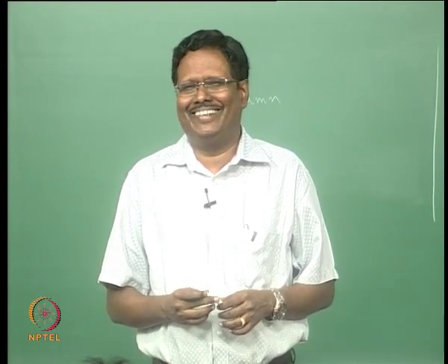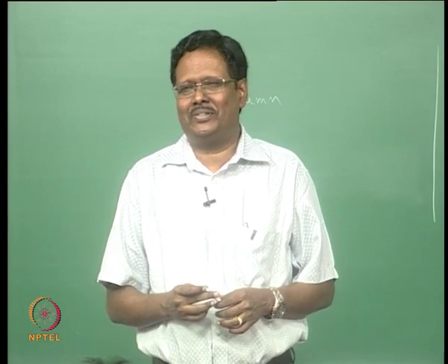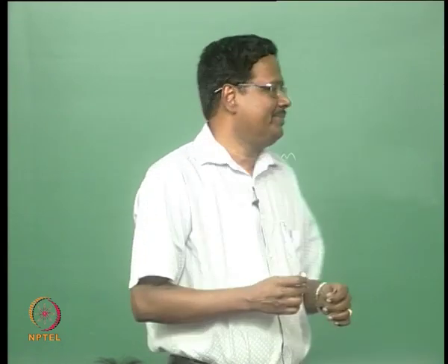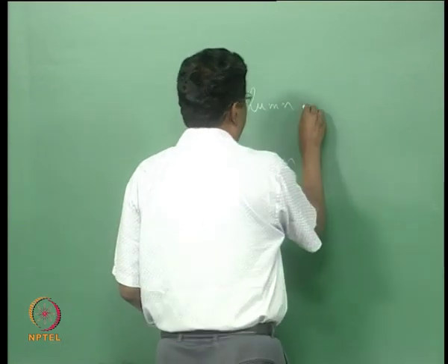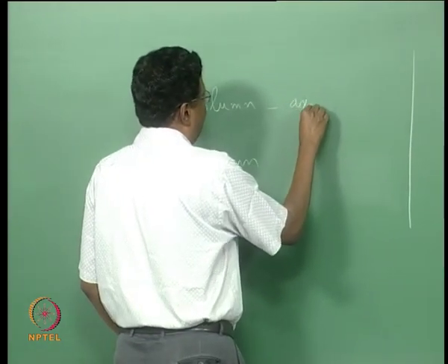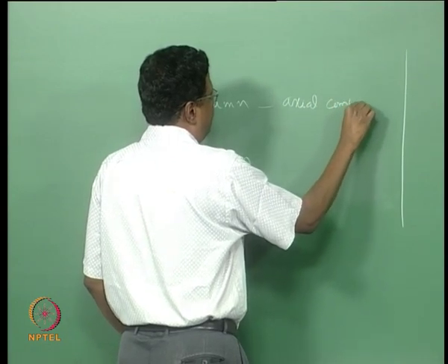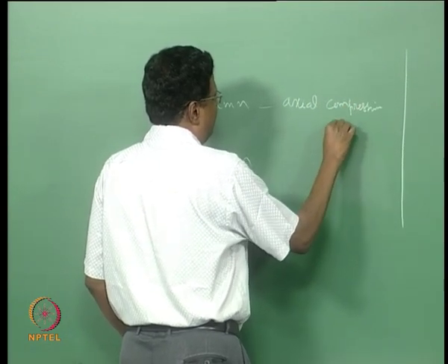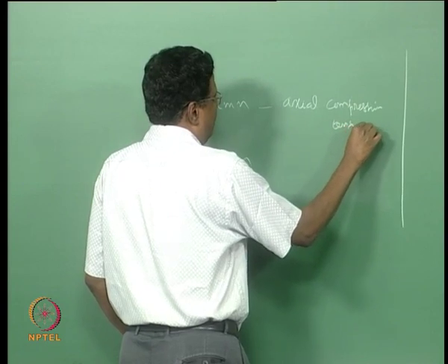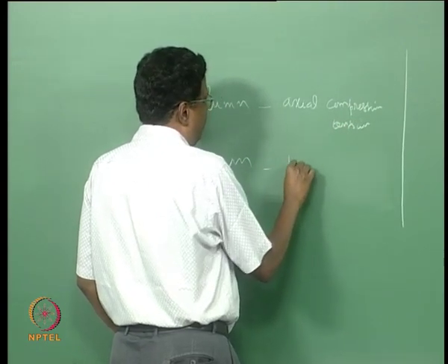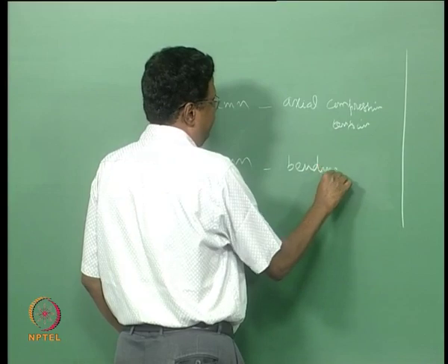Horizontal load, transverse load. See, a column is generally called an axial load member. It can be axial compression or tension. A beam is bending and shear.